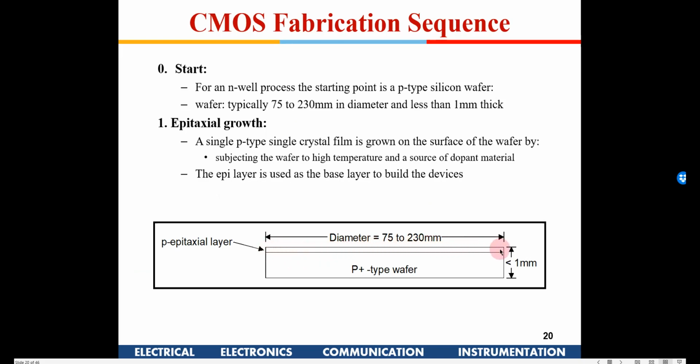Because of the process itself, it will be a very pure kind of silicon layer without any deformities. Because when you make the wafer, you are melting it and pulling it up, this may not be structurally as defect free as an epitaxial layer. Epitaxial is a much better option available.